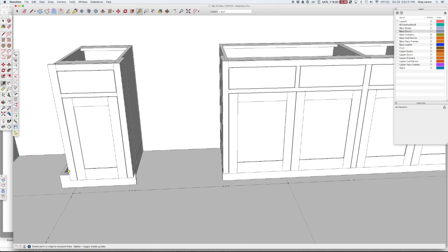And also, if you'll notice, the toe kick base is sticking out a little further so that it intersects with the one coming this direction. Basically, what you've done is you've told CabWriter that this is a cabinet that butts into another, so it knows to put butt style, and it also knows to put an extended toe kick base so that it meets up properly.